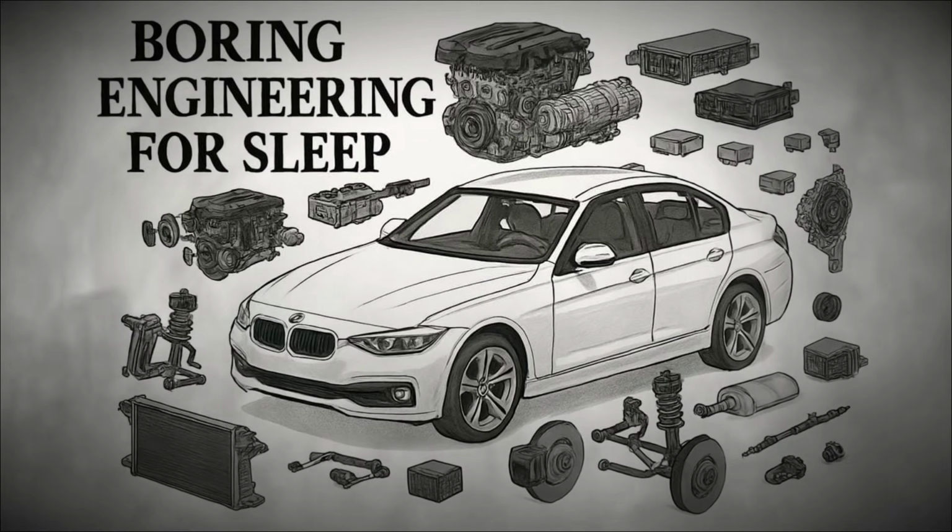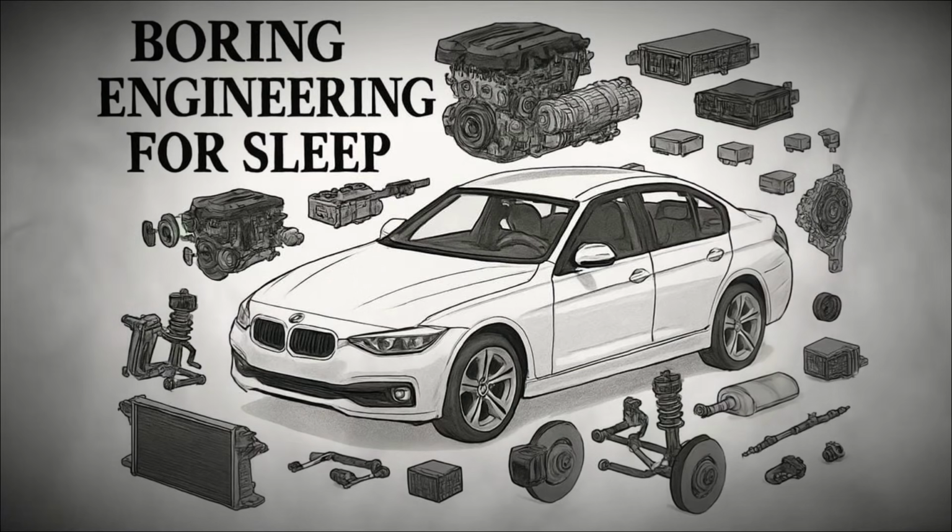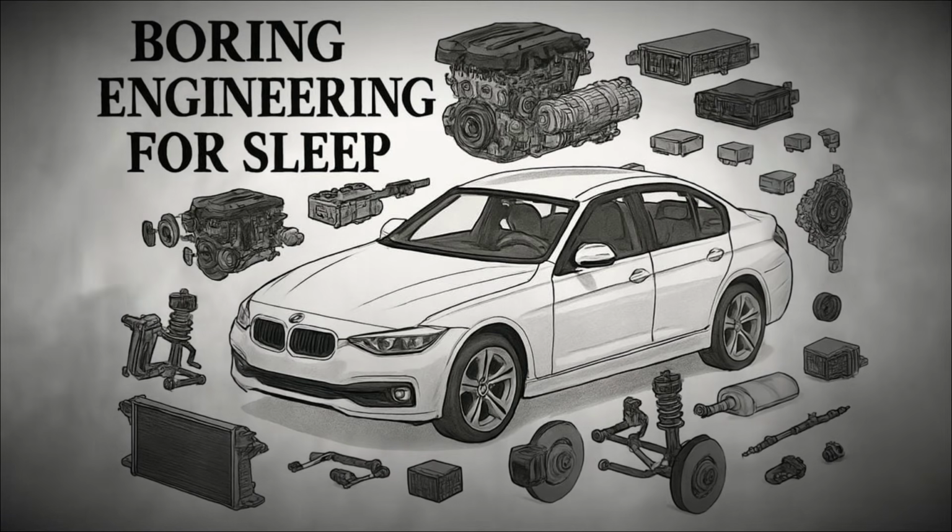In the past, most cars used carburetors, devices that relied on airflow to draw fuel into the intake stream. Carburetors were relatively simple but imprecise, often leading to inefficient combustion and higher emissions. Today, nearly all vehicles use fuel injection, which precisely sprays fuel into the intake manifold or directly into the combustion chamber in carefully timed pulses. There are several types of injection systems.